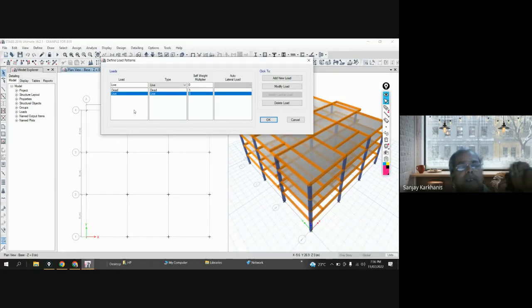So if you are defining, let's say, 10 different primary load cases, and everywhere you will add self weight, is it good? Because if I am defining 3 primary load cases, everywhere it will apply self weight. That means 3 times self weight will be considered. Do we need that? Self weight will be accounted only once, not always. Yes or no?